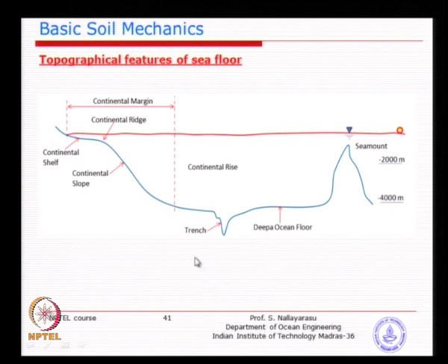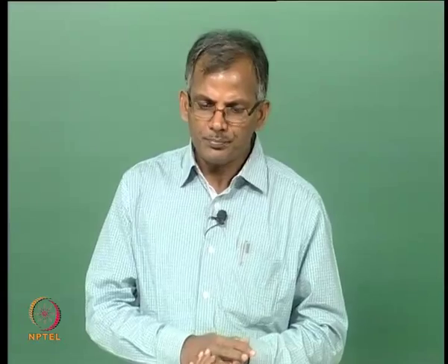You can see here that coarser material will settle here, and less coarse material will be carried further away to the deep ocean. So you will see a specific nature of particle sizing. If you look at the distance away from the coast and go to the deep ocean, the particle sizing is different from that close to the coast. At the same time, depth-wise and across different time periods, the particle sizing differs. This kind of study gives you a very good understanding of what type of foundation is suitable.